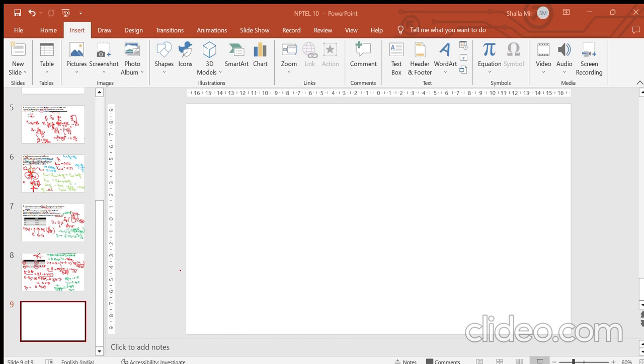For a metallic material, high plastic deformation is possible because you have high dislocation densities, and fragmentation does not occur, because once fragmentation occurs you are just breaking the particles into pieces and do not have the desired strength. Dislocation density is simply how many dislocations are present per unit area or per unit volume of the sample. If you have high dislocation density, you are able to deform a material to a larger extent, with higher plastic deformation.